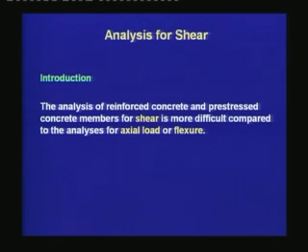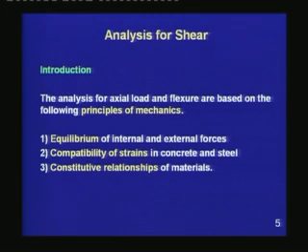The analysis of reinforced concrete and prestressed concrete members for shear is more difficult compared to the analysis for axial load or flexure. The analysis for axial load and flexure are based on the following principles of mechanics: equilibrium of internal and external forces, compatibility of strains in concrete and steel, constitutive relationships of materials.